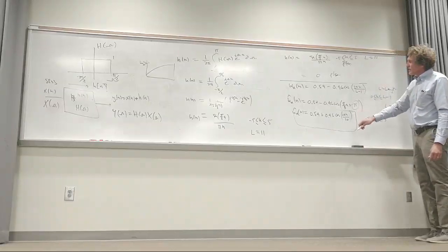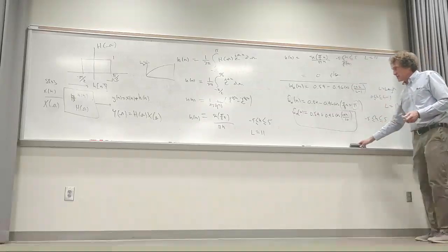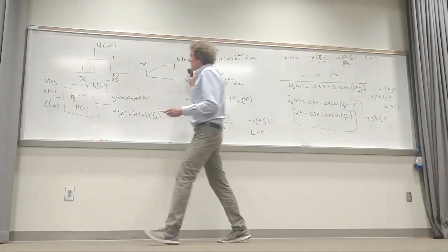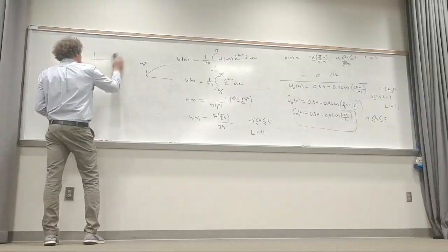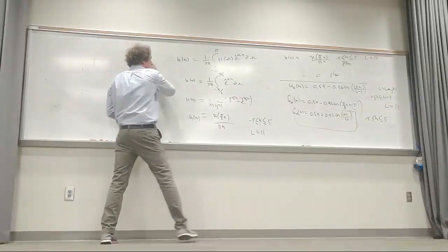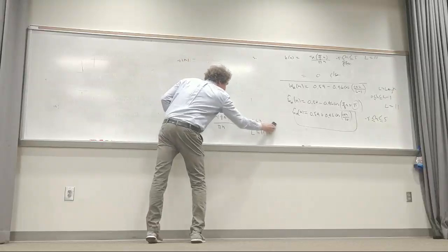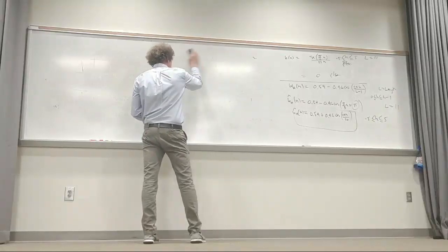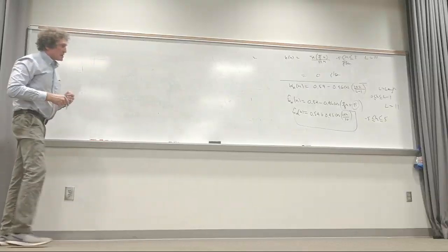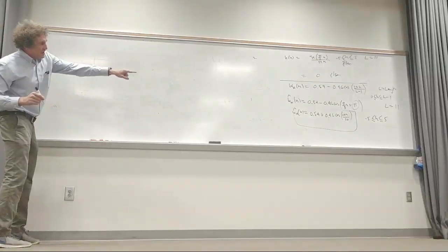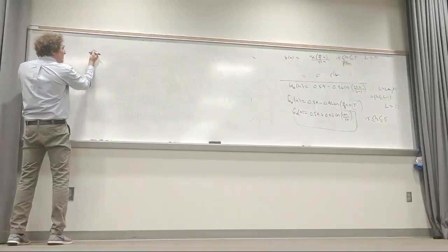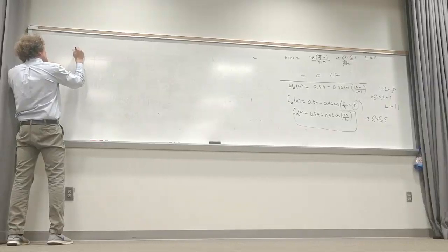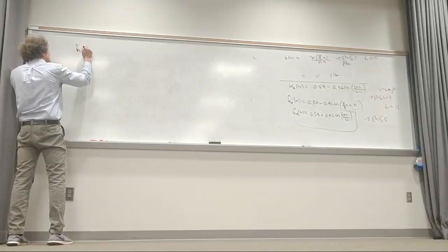Now I take this window times that function, and I'm going to do this. You'll see that there's a shortcut to this, but I need to go through this because this is how the book lays it out. And in general, this, I believe, is how it's done when you do filter design. Dr. Reeves would actually be the person to talk to you about this. So now I'm going to take that modified Hamming window and multiply it times h of n. And now I'm going to get my actual, he calls it h, well, this is not quite adjusted. It's h tilde of n.